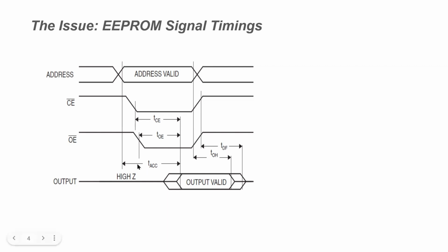My TTL computer clock runs at 4 megahertz with a 4-phase clock, so our individual clock signals are 250 nanoseconds. The NOT clock is active for 250 nanoseconds. So this time period for the EEPROM of being basically undefined is over half of the period of our clock signals. This is a problem.